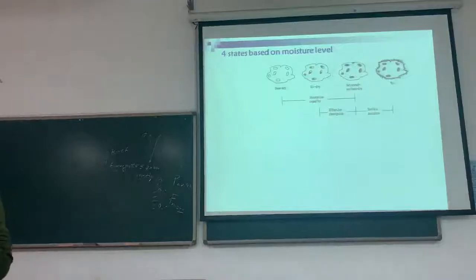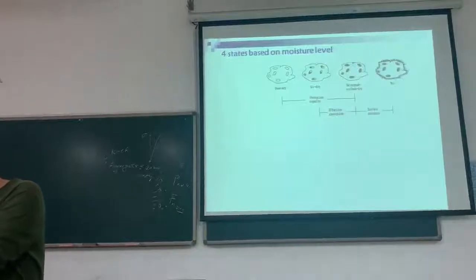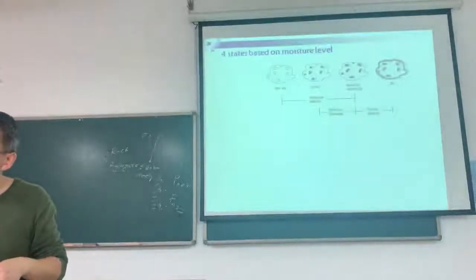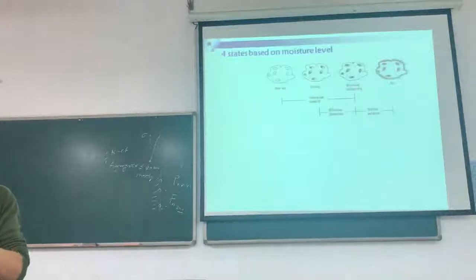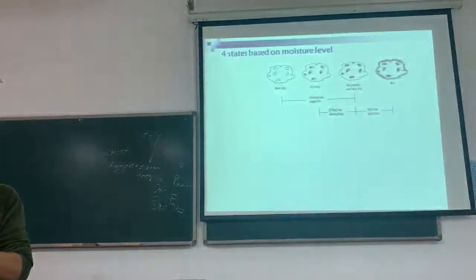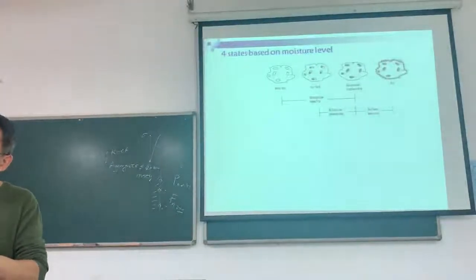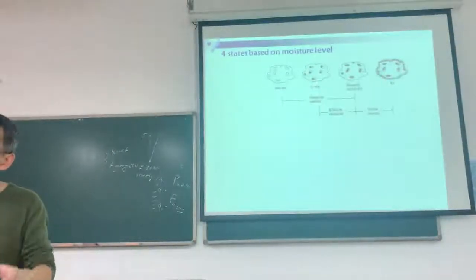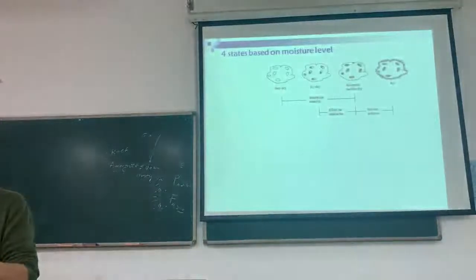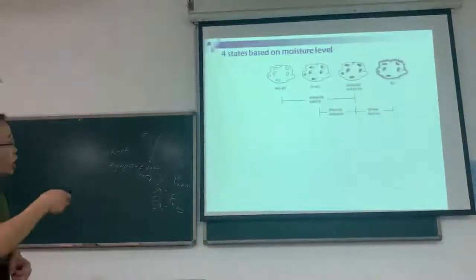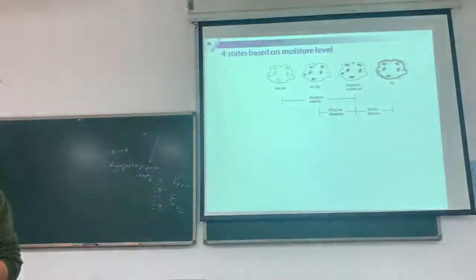If we want to construct an asphalt pavement, we need to get the aggregates from outside into the laboratory, and then conduct a lot of experiments to decide how many aggregates are needed for the asphalt concrete, and then how about the content of the asphalt needed. So in the laboratory, when we conduct experiments, we must use the oven dry aggregate.